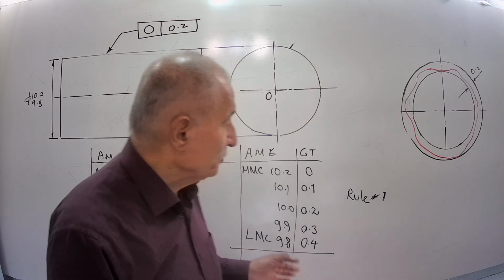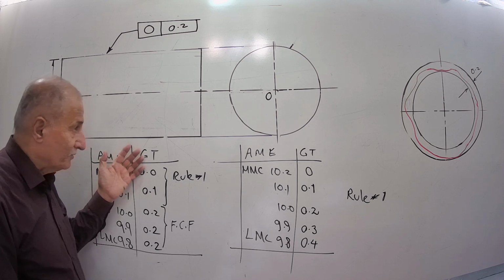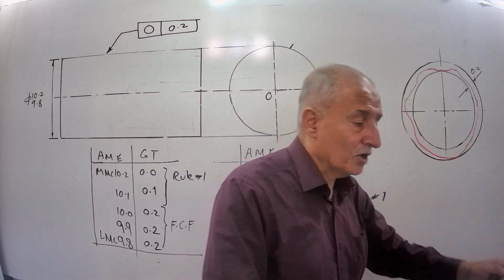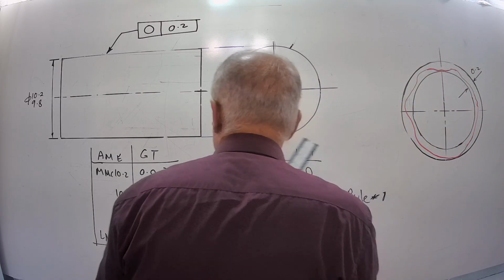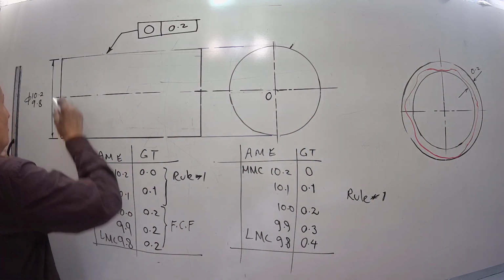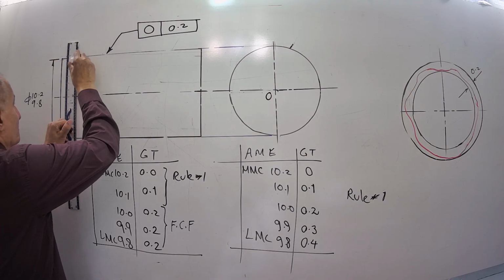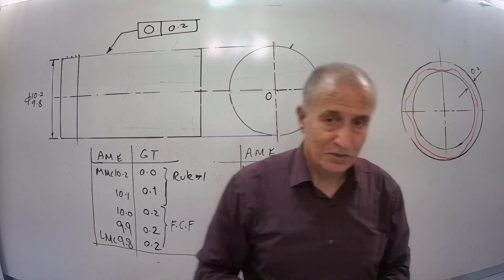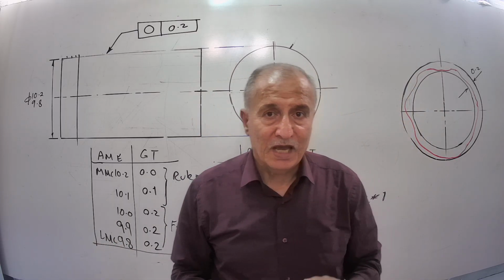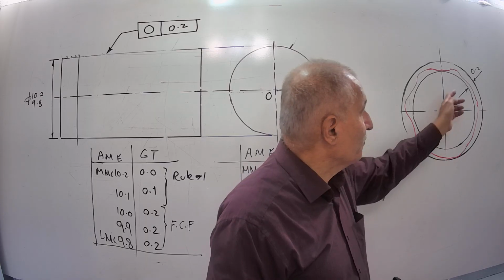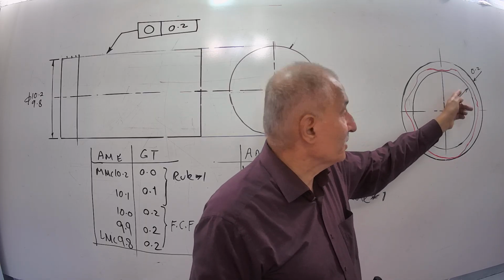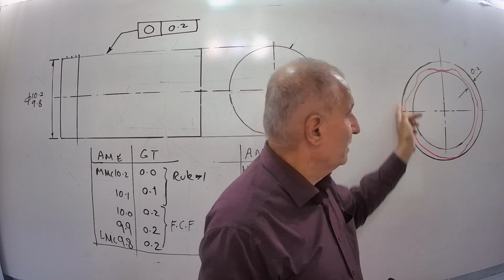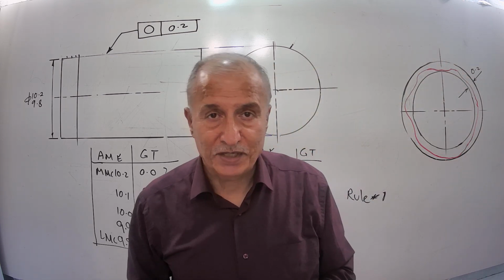Any individual cross section, assume that we have this case. Any individual cross section that we cut of the object, or we measure all individual cross sections, for example this one, by a CMM machine. The CMM machine can give a contour of any cross section, and we put the contour between one largest inscribed circle inside and the smallest circumscribed circle outside.